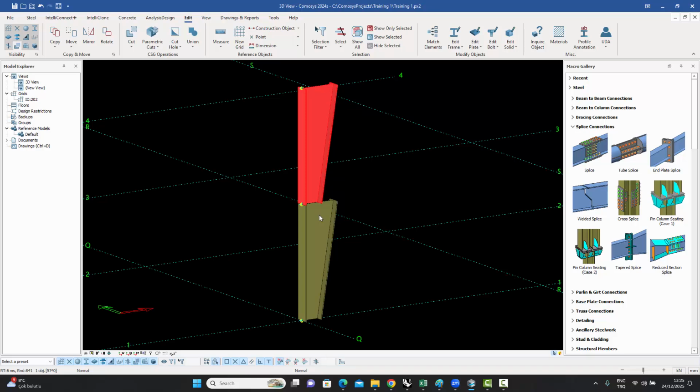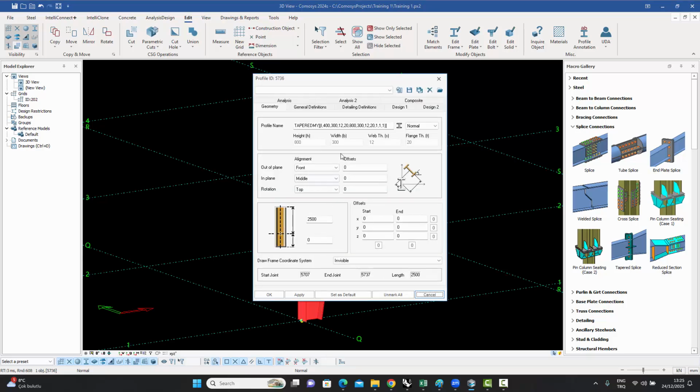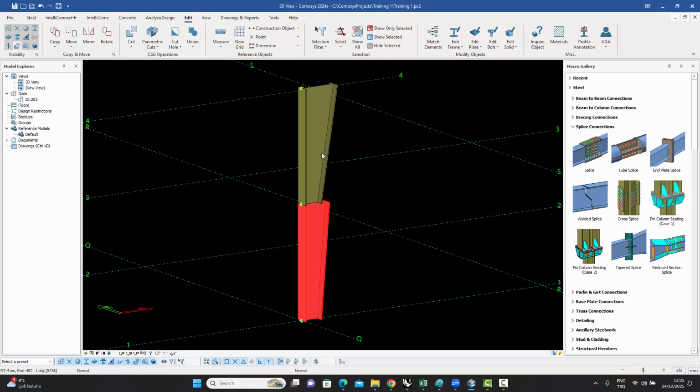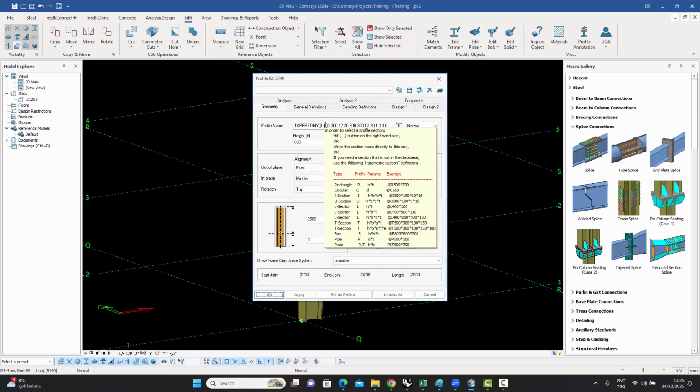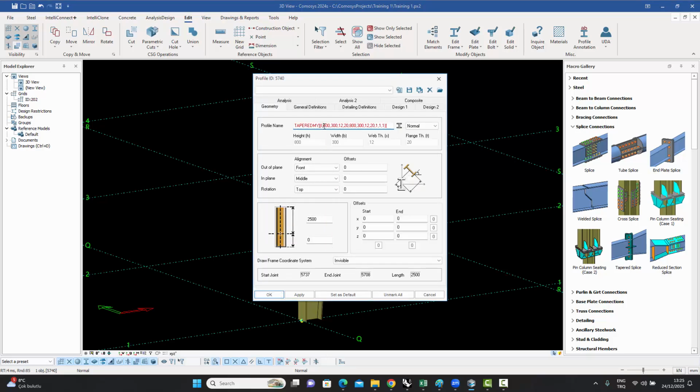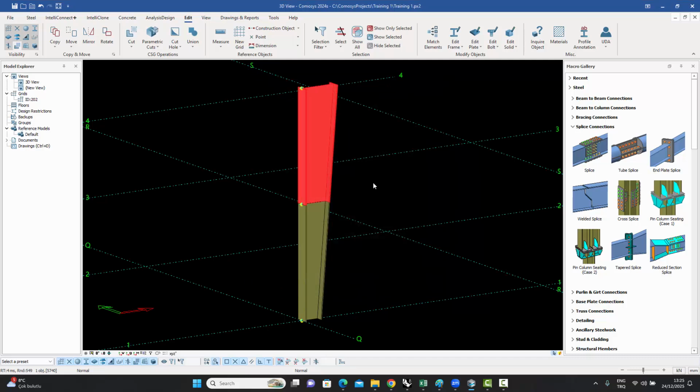I know in the middle it should have been around 600. So I could click on this one, and instead of 800, I could make it 600 like that. And then click on this one and say that instead of starting at 400, it starts at 600 rather. And when I do that, I get the exact shape which I wanted. In this case, it's exactly 600.